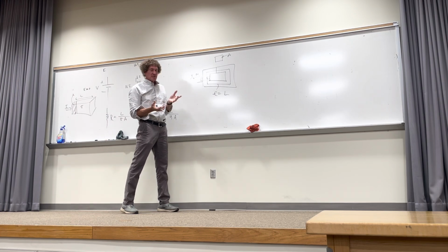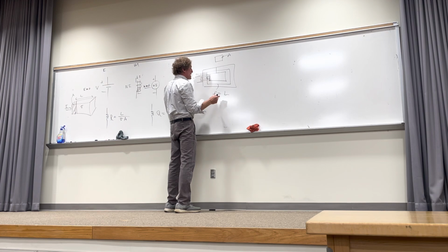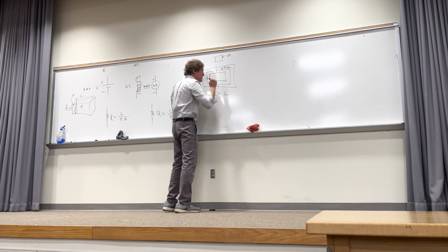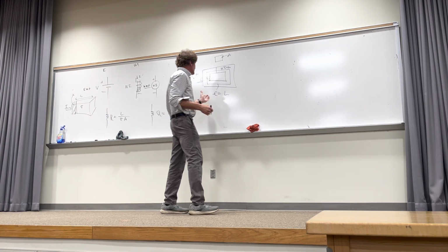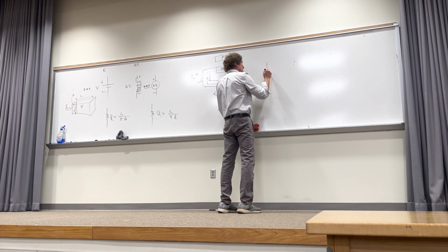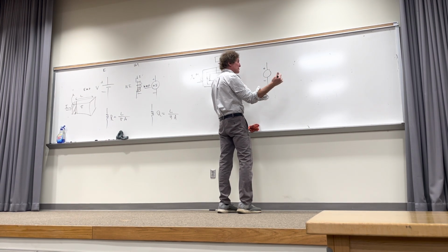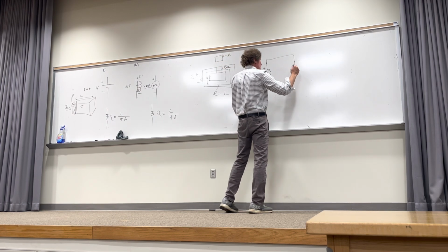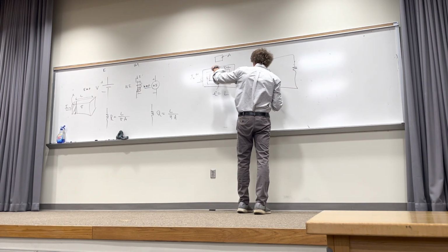And the bar here, I'm trying to show you an iron core for a transformer, if you understand. Inside this bar, it has some permeability mu, which is much, much greater than mu naught, or mu relative, you should say, is much, much greater than 1. Then I can say the electrical analog in terms of components would be a voltage here, Ni, and a simple bar reluctance that is associated with that entire path around there.